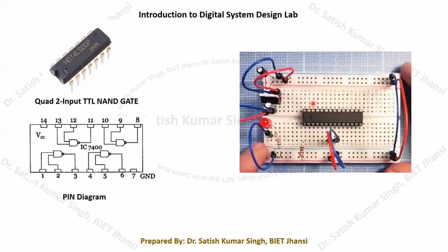So just for the sake of completeness, remember that in the breadboard, we will have certain horizontal connections at the top, and here it will be vertical connections. Okay, and again in this section we have the vertical connections, and again at the bottom side we have the horizontal connections. The meaning is that all these holes that you are able to see are internally connected horizontally. Okay, and here the holes which are in this particular segment are connected vertically.